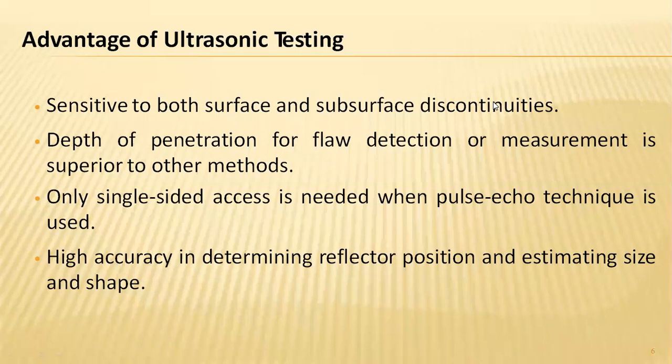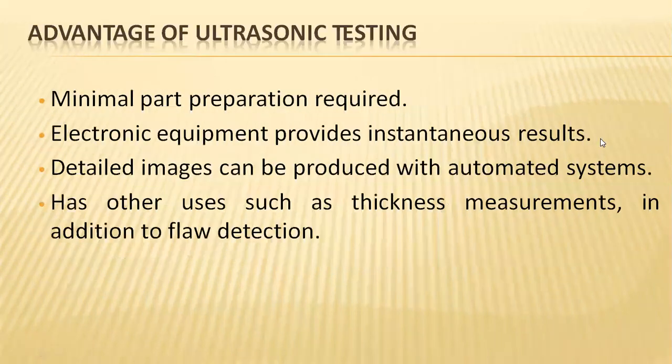So when compared to the previous non-destructive evaluation techniques, ultrasonic testing has a much greater depth of penetration, and even beyond those limits, those factors can be nearly examined or estimated by this ultrasonic testing process. There is another greater advantage: minimal part preparation is required, but not to a maximum level.